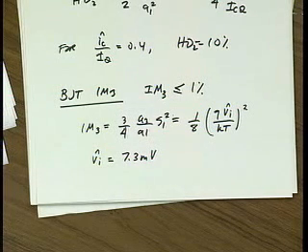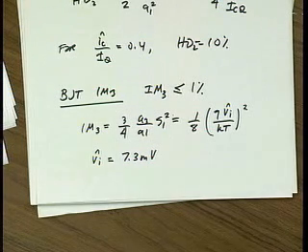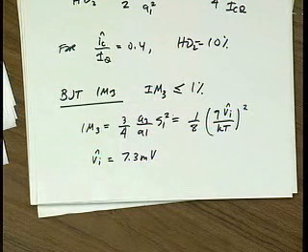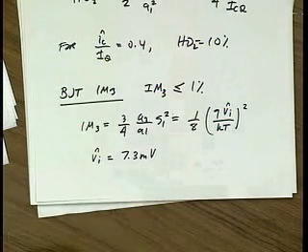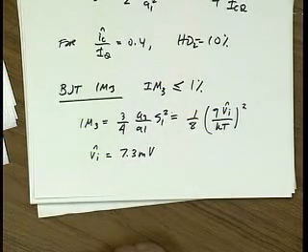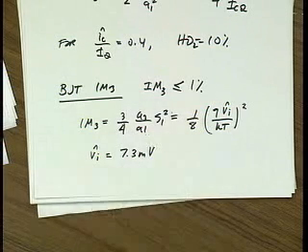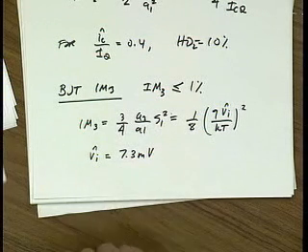7 millivolts. Usually we like to send healthy signals which are much above the noise floor. And in some systems it may turn out that 7 millivolts is too small. Let's say I'm going to send a signal for 10 miles, and I know it's going to get attenuated by 60 dB. Well, I want to drive it so it's large enough so that by the time we get to the receiver, it's still, let's say, hundreds of microvolts or tens of microvolts. So certainly I'm going to need to amplify a signal bigger than 7 millivolts. So this common emitter amplifier, very simple, has a serious problem with distortion. It's very, very nonlinear.